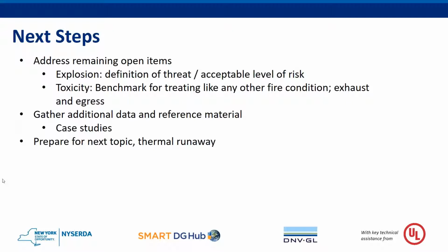Hi, this is Victoria again. I do want to make sure that I underline that scaling from cell or module level data up to full unit level data is not what was discussed or approved or agreed to verbally in these conversations. The conversation that we had around variability on systems is completing the full course of the UL 9540A testing, so cell, module, unit, at least. Installation, not necessarily. Cell, module, and unit, at least, of the worst case scenario, in which case you can then use that data. So it's not that you can test one cell and multiply it by the number of cells